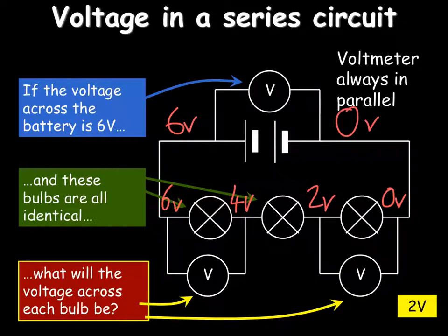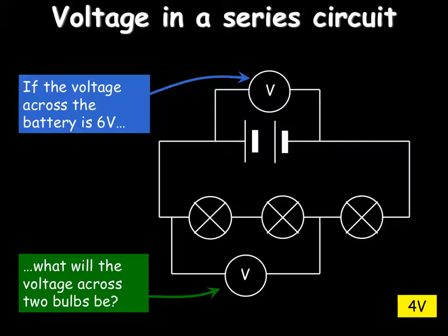That's called the potential difference. And it's also, as you can see, why we measure the voltage across the instrument. We're looking at the drop of voltage. If you take 2 of these bulbs, of course, then if you have 6 volts there and 2 volts here as in the previous, now the drop is 4 volts, which is what you measure on the voltmeter.